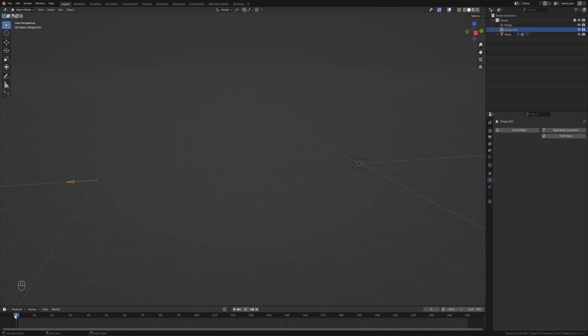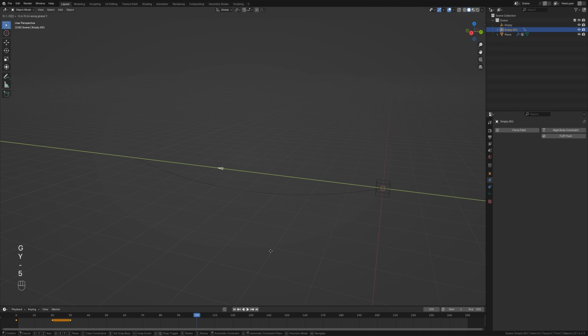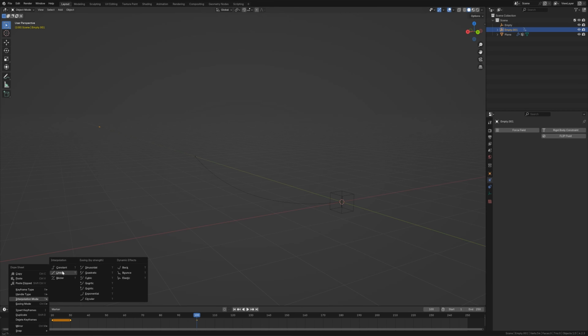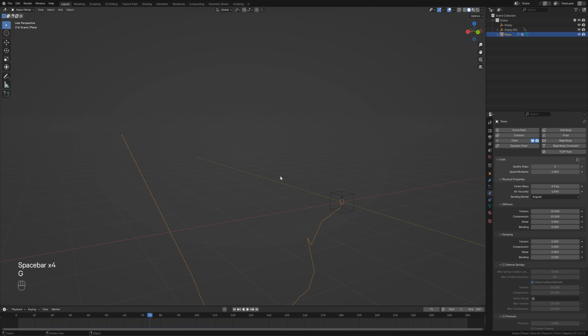Let's set a couple of keyframes here. Set the initial position for the hook empty, then another one at the world origin at 20 frames, and let's add a duplicate of that to 30 frames, which will be the launch moment. And then at like 100 frames, let's move it to -50 on the y-axis. You can move it wherever, but I'll set it to 50 for the demonstration. Now with these keyframes, you can see that the rope sags down and then tightens as the hook moves away.